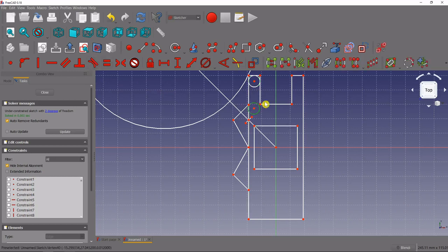Now you can see that we have two identical circles. This one can still move in space, but this one is actually locked because of the three tangent constraints. So this circle, we're going to add a tangent constraint to the outside edge. And then we are going to locate it. You can go crazy trying to figure out what to locate these in reference to.